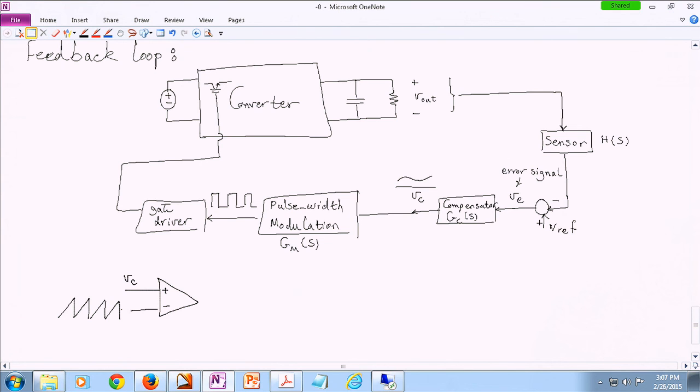Then at the end of your switching period, you can discharge or reset this capacitor, so the voltage of the capacitor jumps to 0. So you charge it, jump back to 0. Charge it, jump back to 0. So you're creating a kind of a sawtooth waveform. And the output would be the difference between VC and this sawtooth waveform.